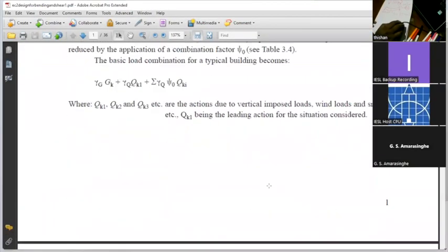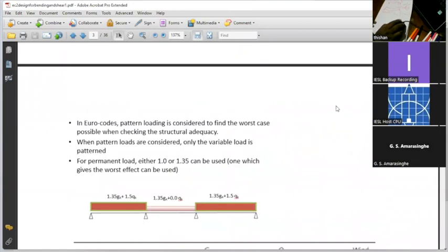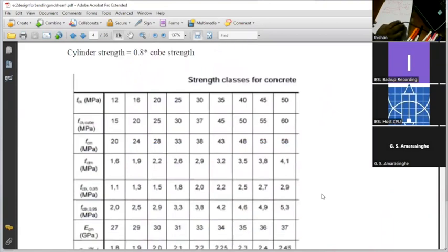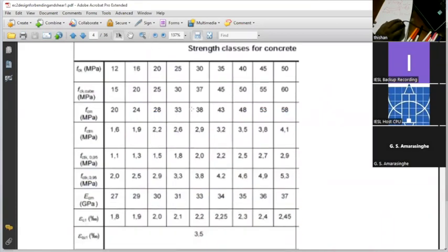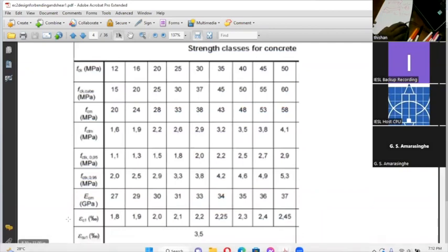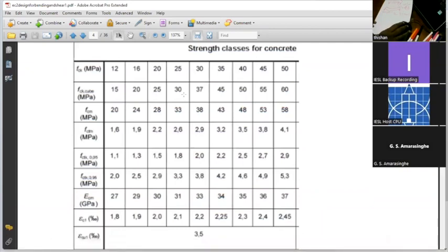So this is the note that we are using for other subjects. Here you can see the strength of concrete. So generally, if you go with the cube strength, when we do post tensioning, in the early days we used 30 megapascal concrete, and we did the transfer around when it reached about 22 or 25 megapascal, right? So we did the transfer around this.